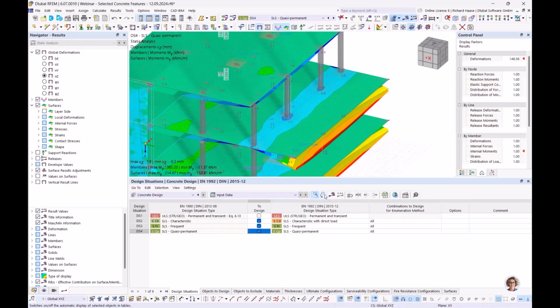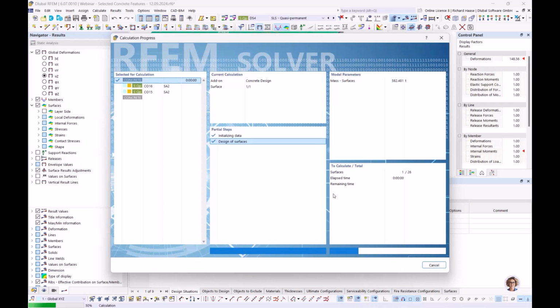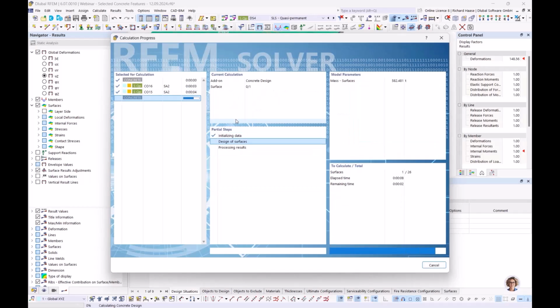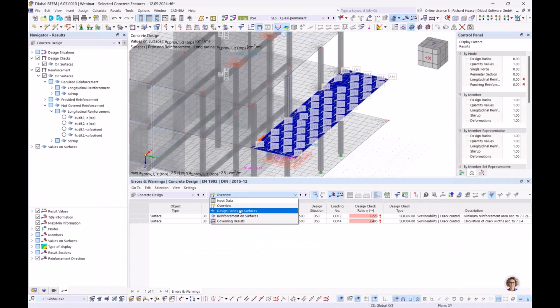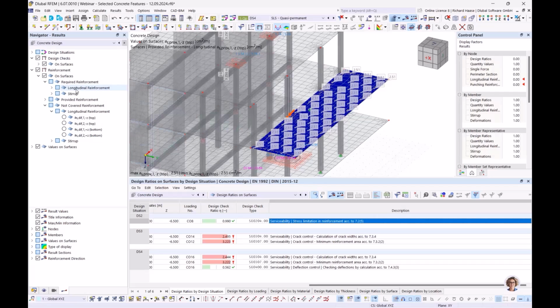and 130% maybe, well, remember, for the steel stress. And now when I calculate it, okay, then you see 99%. And why? Because now we have not only the provided reinforcement, we have also the required and the not covered reinforcement.